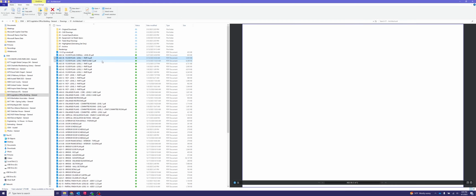One other thing I want to take note of too is whenever you have upper cabinets, it is really important to look to make sure if there is a ceiling or a soffit that sits right above your cabinet. If no soffit or ceiling exists, that's great. You don't have to do anything different here. If a ceiling or soffit is touching the top of your cabinets, you do have to make sure you put in that 3/4 inch reveal that runs all the way from left to right of the upper cabinets up top.